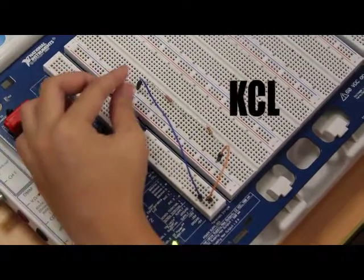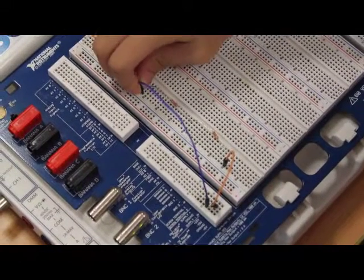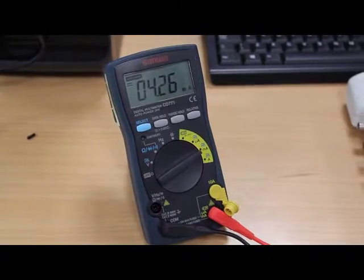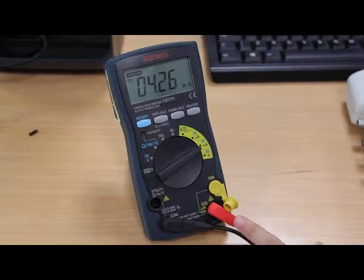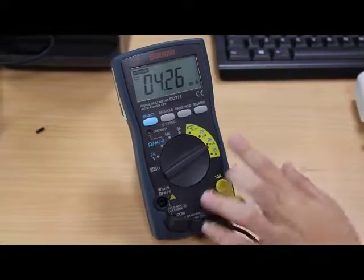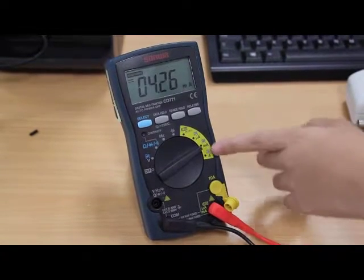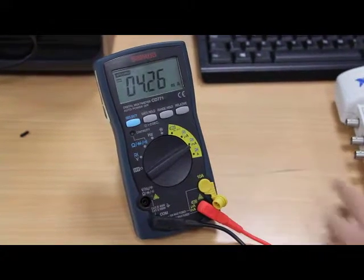To measure the current in KCL, first you have to unplug the power supply cable to another node. You can put it here, and then just measure it. To measure the current with the multimeter, you have to unplug this red one from here and put it right here. There are a few different options to measure ampere. In here, this is for ampere, this is for milliampere, and this is for microampere. But for these two, you have to put it here, while for ampere, you put it in here.